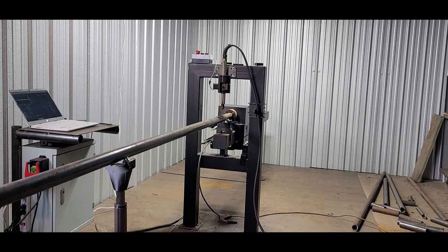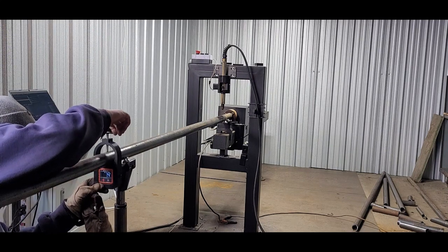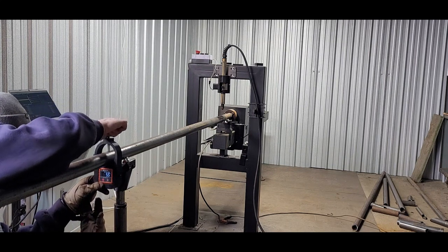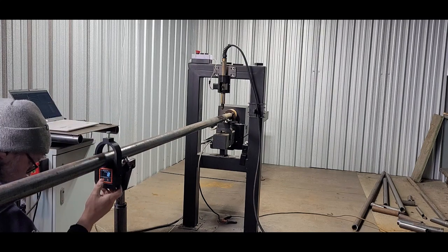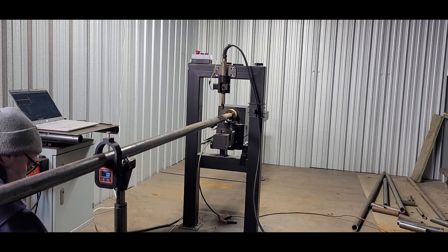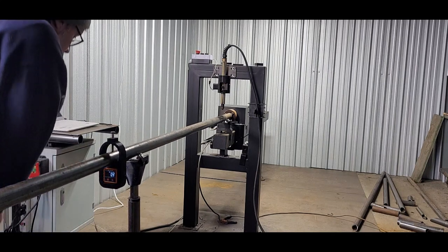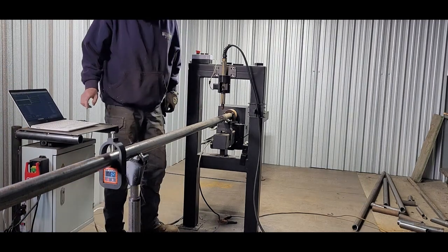So the first thing that we're going to do once we get to the machine, we have this pipe now sitting in the rollers. What we're going to do is put on an angle finder. We're going to clamp the angle finder to the machine, and then we're going to zero out that angle finder. And what this does is it allows us to put the pipe back in exactly the same orientation for the rotary axis. So when we spin this pipe around after the first cut, we'll end up using that in order to zero out the pipe in the chuck.